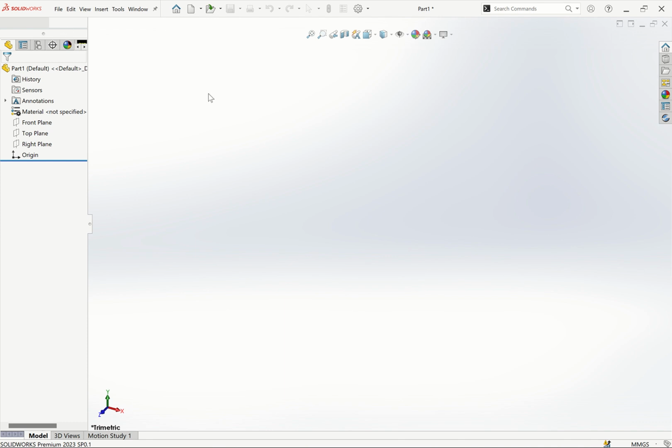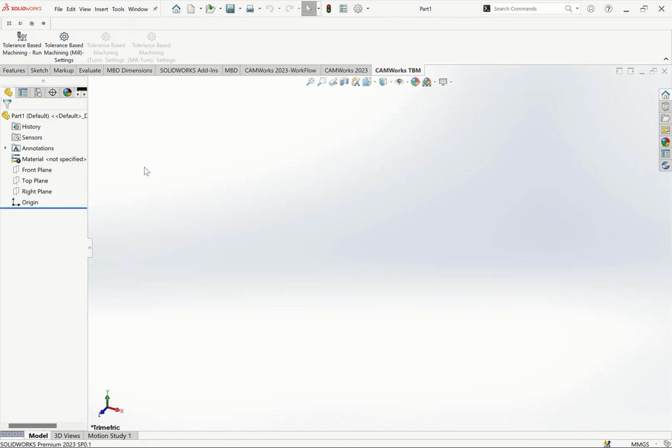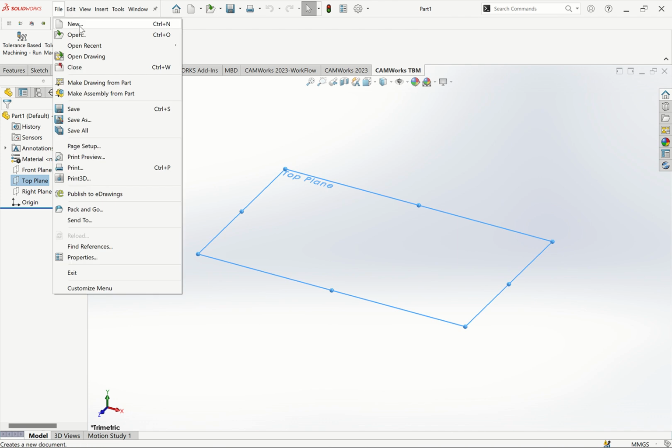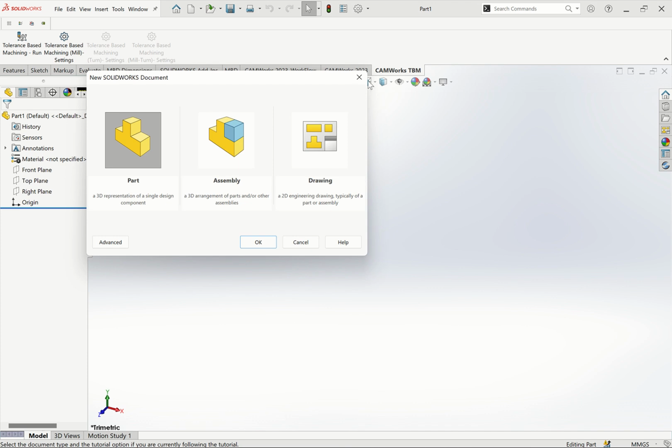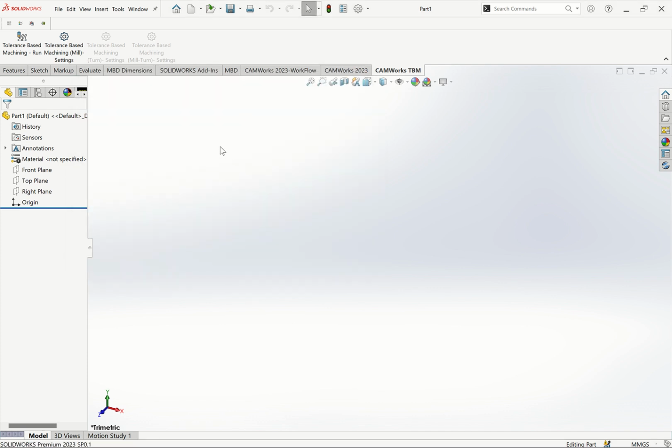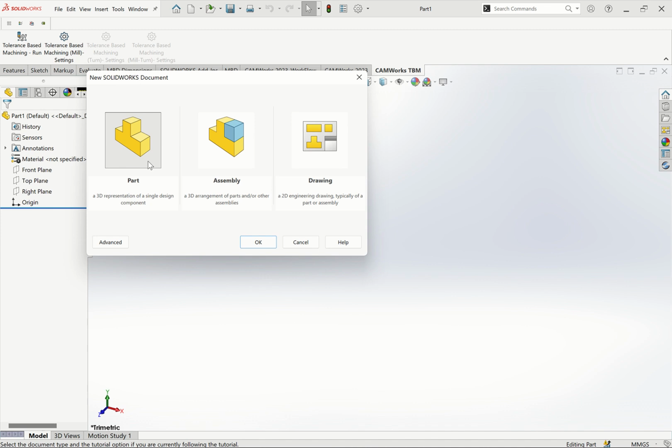Once you open your SolidWorks, I'm using SolidWorks, by the way, that is the software I'm using for design. So quick way, just file, new part, or shortcut, click Control N. SolidWorks has this, be able to do part modeling, that is 2D and 3D modeling. You create 2D sketches, then you convert to 3D sketch, then 3D models or features.